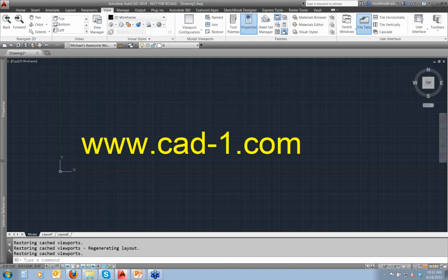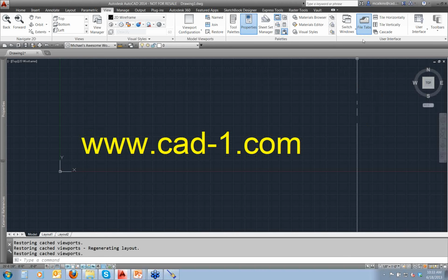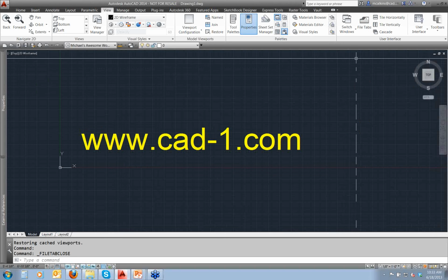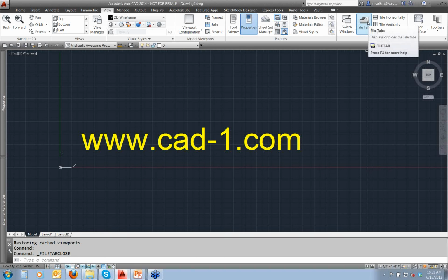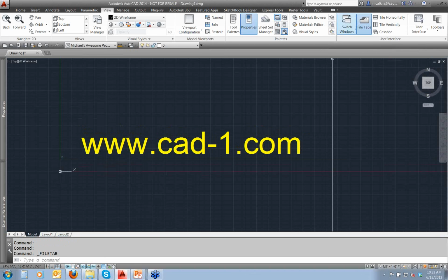If you come to the View tab here on the ribbon, you'll notice over here there's a user interface panel, and right there we have file tabs, and it's blue. That means it's on. If I click on that, it will hide those file tabs. It's that easy to turn them on and off. Maybe you want to toggle them quickly because some days you need them, some days you don't. That's the quickest way to access those.